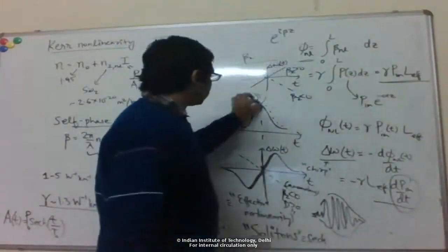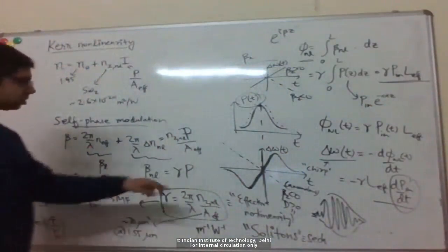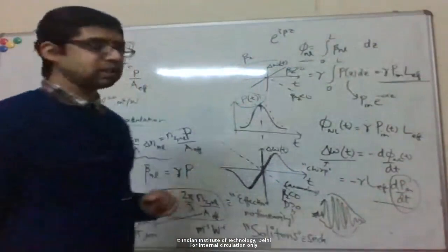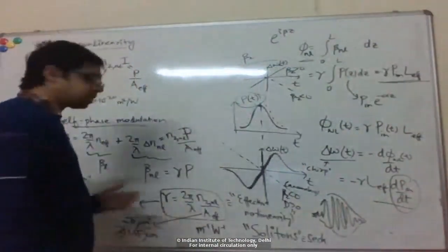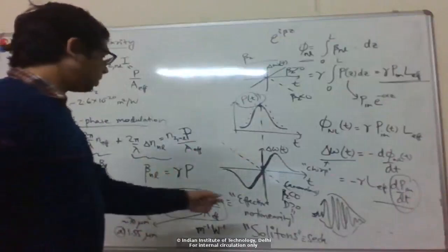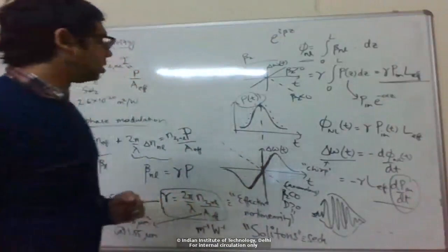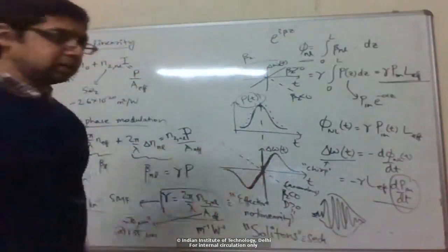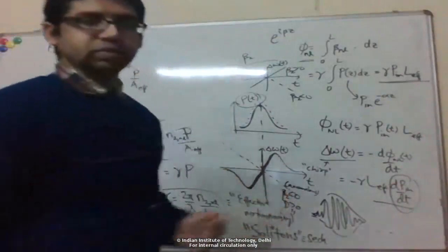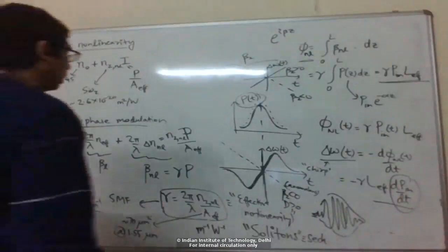Even though I launch at the input with some particular power which satisfies the soliton criterion, on propagation after some distance, you can see that the power will actually decay, and the soliton condition won't be met anymore. So this will change because of the loss. So you can see that including loss, the soliton condition is difficult to satisfy, but still there are some tricks we can do.